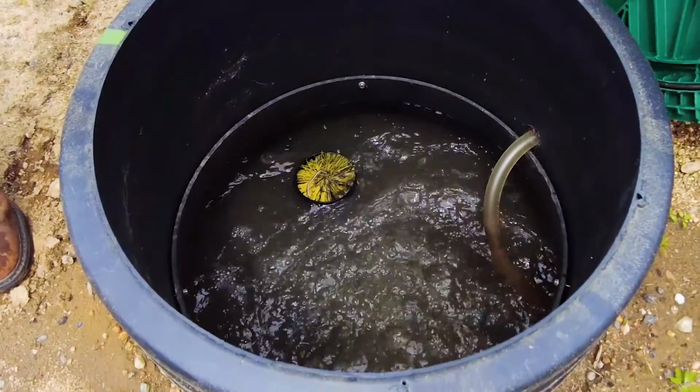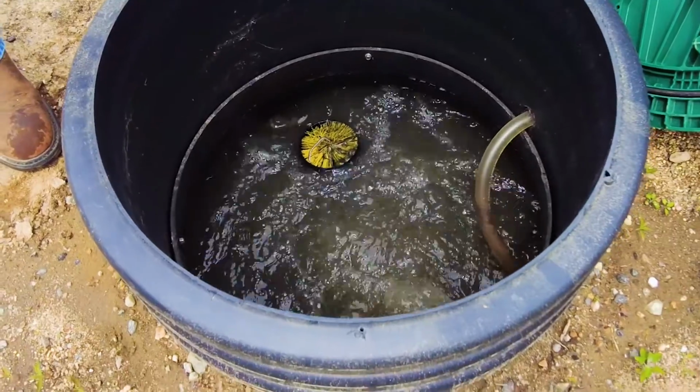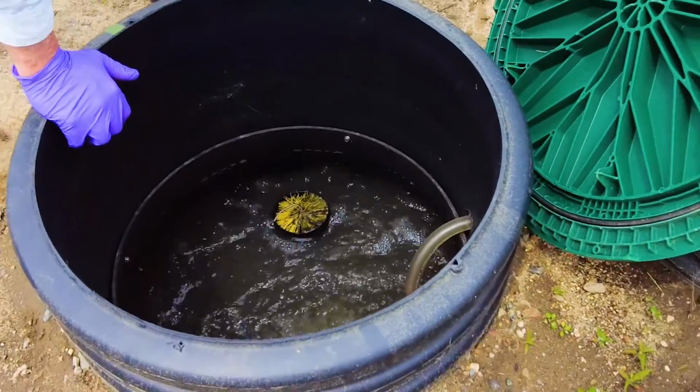And with samples, we have effluent and we have influent. What's the difference between those? Well, the effluent is the sample before it goes into the leach field. In most cases, it's right before it is released to the environment, where the influent is what is exactly coming out of the house, which is probably one of the tougher things to sample. And in some alternative septic systems, you can't sample it adequately because there's a mixing that occurs within the unit process that prohibits you getting a clean influent sample, if there is such a thing.